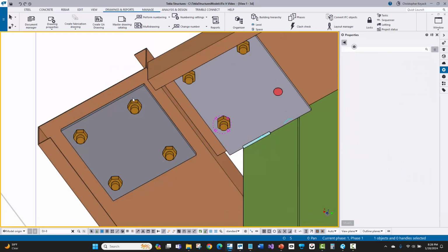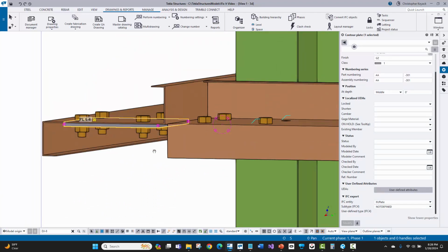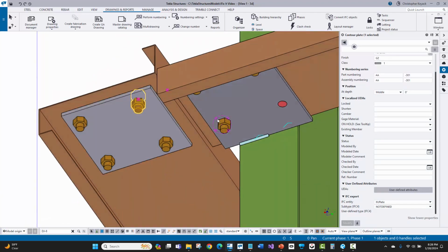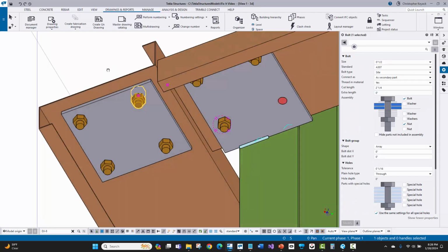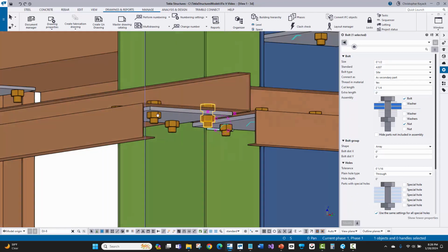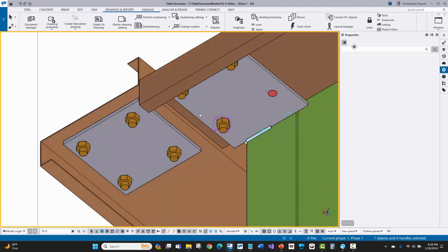And now that's fixed. Now, technically, this plate does need to move over, and we probably need to bolt these together, especially if we want to make sure that we don't have any problems with the bolt length. Let's see, what are these A307s? Yeah, 1/2 inch A307. So I'm probably using a standard bolt length that might work on that, although those are fairly thick. But at least for now, I have separated those bolts.